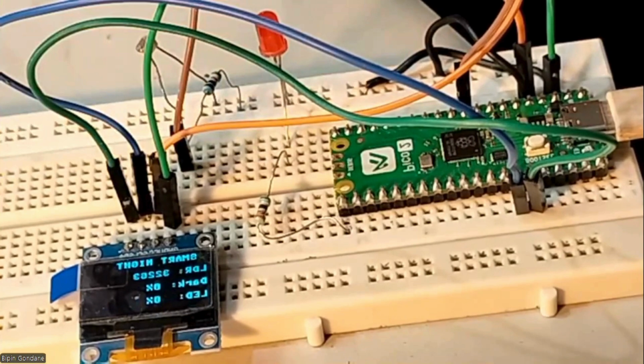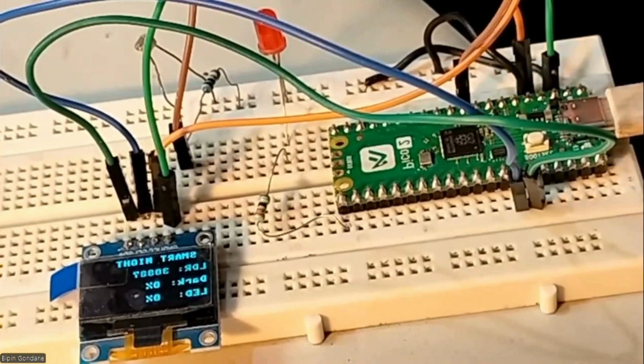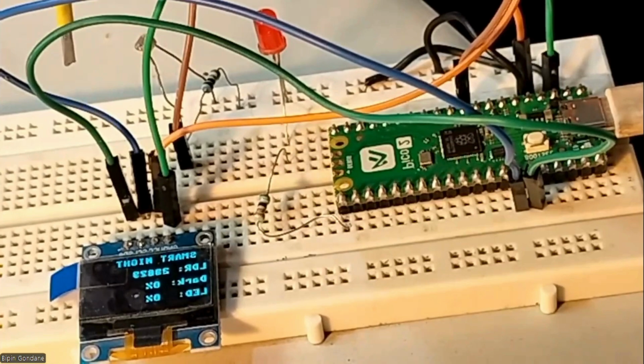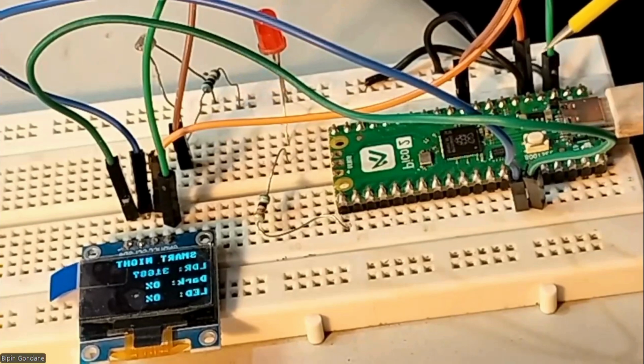This is my Pico board. It's written over here, Pico-2. It is working on MicroPython, which we have already discussed. Two connections from here, pin number 4 and pin number 5, go to the OLED display. That is SDA and SCL. It works on 3.3 volts, which I have taken from pin number 3 over here, and from there I have taken the supply for this.